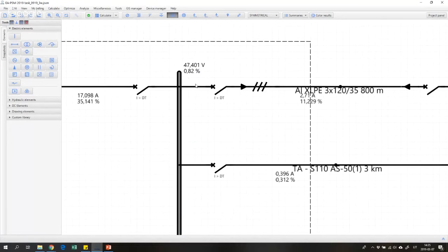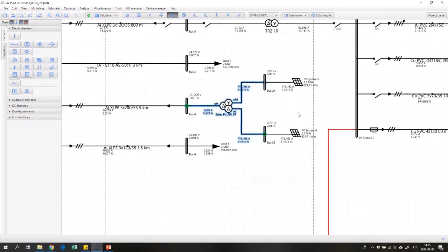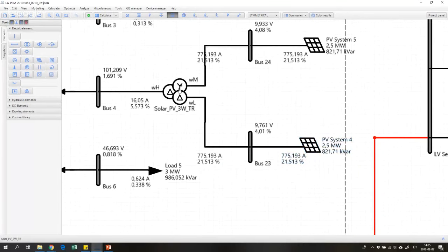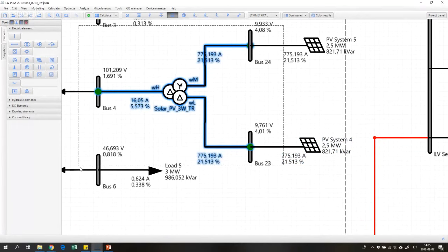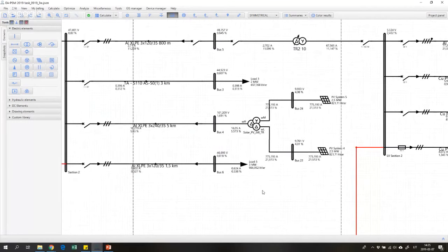So with this kind of transformer, we solved the harmonic problem, and we haven't used any filters, just changed the phase difference of the separate harmonics so that when they sum up, they are close to zero. So it means that there are various solutions. For example, this one is quite commonly used in India, in Asia, where they have high ambient temperature, and it causes harmonics plus high ambient temperature. It causes additional stress to equipment.